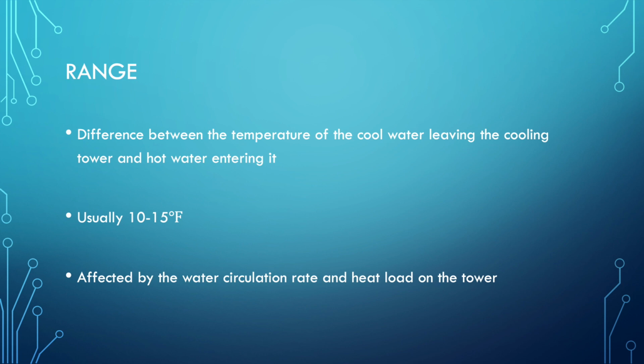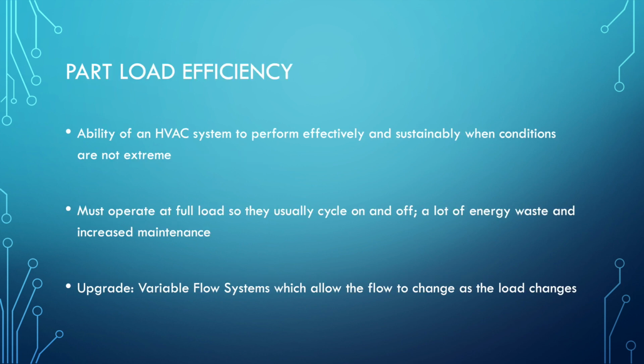It's affected by heat load and water circulation rate. And water circulation rate affects this because that changes the flow rate, which then changes the range. A higher flow rate will dictate the temperature more. Part load efficiency, I'm going to talk about next.